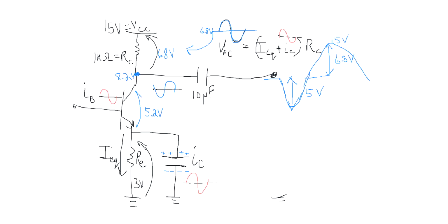It's going to isolate it from that DC voltage and is only going to pass through the AC alternation with a 5 volt downward peak and a 6.8 volt upward peak. The reason why it is uneven is because VCE and the voltage across the collector are not equal. So you have a different amount of room on both ends.